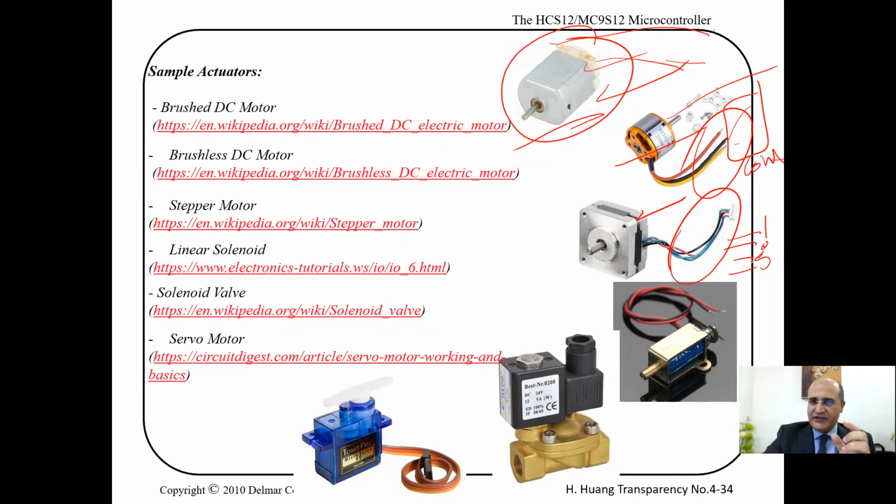What is the step size? It depends on the characteristics of the motor. To move another step, you write a 0 1 0 0. Another step, you write a 0 0 1 0. So you keep moving the 1, and then you go back again. This order is important. For example, if you move the 1 across the 4 lines and put it in a loop, maybe you will have to repeat the operation 50 times for a full rotation. To keep going, you need to keep repeating this in your code.